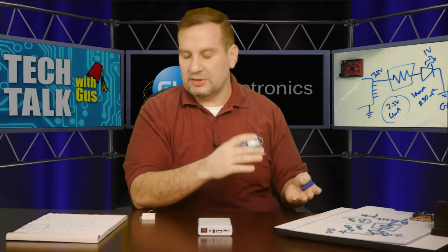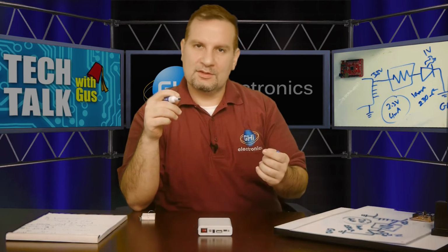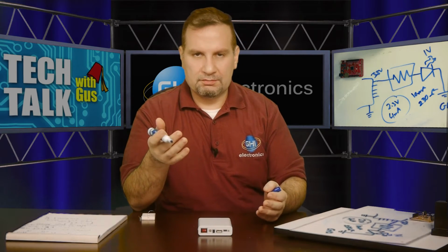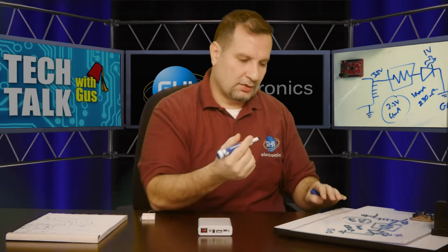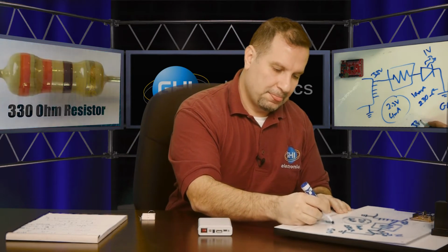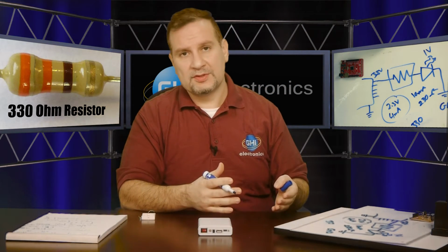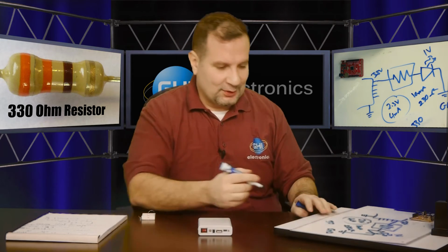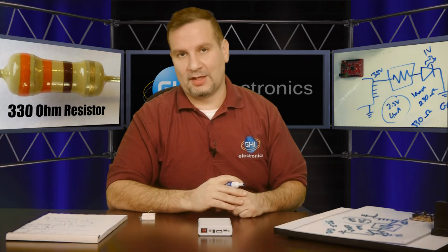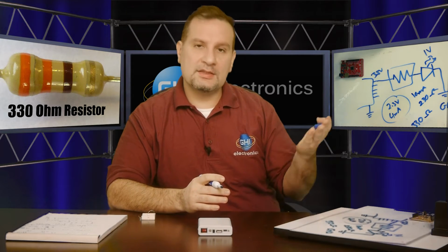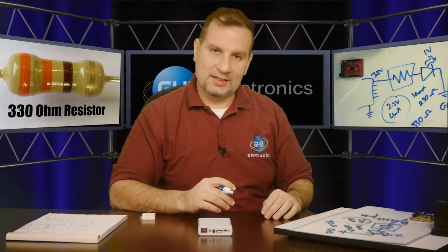So the value is between 230 and 575, and that's why most circuits, when you're working with embedded systems, you would see an LED connected to a resistor that is about 330. This is like a middle ground. This is a very common value, and if you're going to work with circuits, you have to have 330 ohm resistors in your drawer. This is something you would need sooner or later for LEDs and for other purposes as well. So 330, this is one thing that you should have.